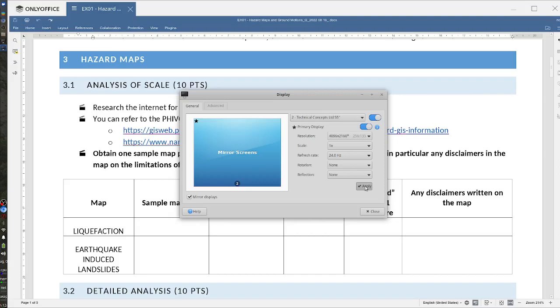For example, if there's a fault structure here and there's a ridge that might be a continuation of this fault, you might have to make that judgment. Or as I've said before, in practice we usually just use 100% of the active fault length because we're not really sure if this is the whole length of the fault.